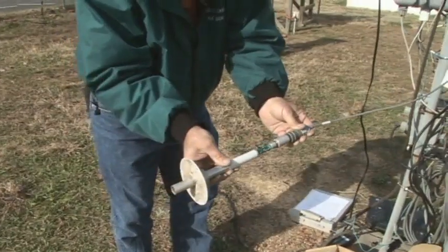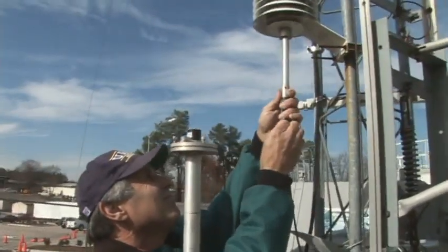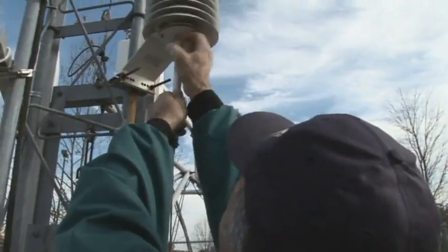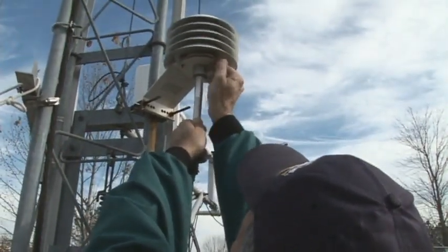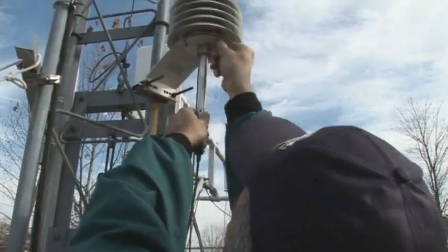If the responses to the calibration solutions are within tolerance, replace the probe in the housing. If not, adjust the response of the sensor or DAS and perform the calibration a second time to reaffirm that the adjustment is within tolerance. This concludes the calibration of the temperature and relative humidity meteorological measurement systems.